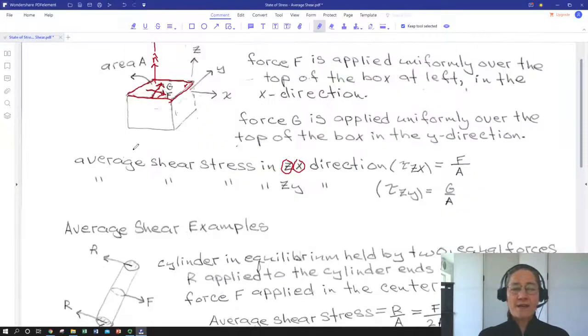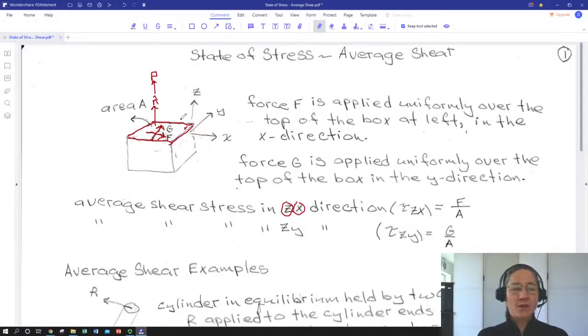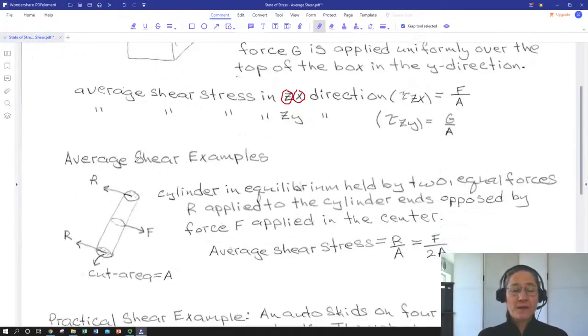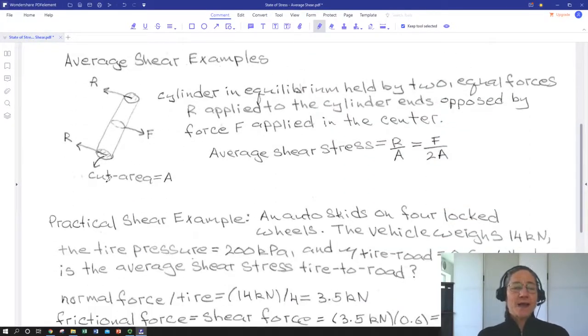We're assuming that we don't have to deal with single points that are significantly higher, even though they might be there. So how would we use this? Anytime we're loading something sideways. Let's take that same cylinder we had in our definition of normal stress, and rather than loading it along its axis, we're going to load it with force R parallel to its ends. Then we put a loop around it in the middle and yank it the other way, so it's in static equilibrium.